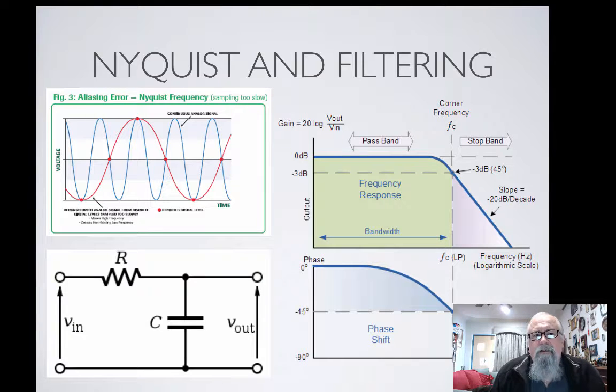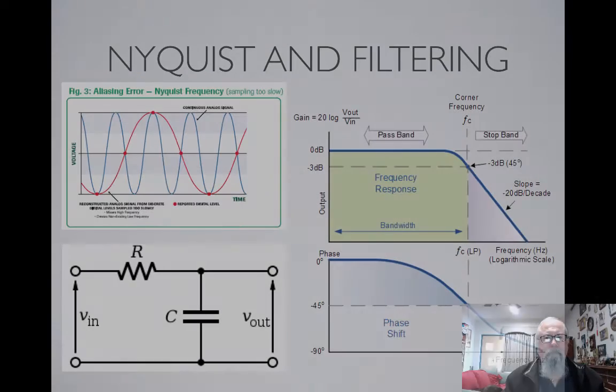So what would happen is our reconstruction of that signal based on the samples we have received would be completely different to the signal that we wanted to actually capture. And this is because we are sampling at too low a rate to actually capture the information contained within the input signal. And we're missing major parts of it as well.